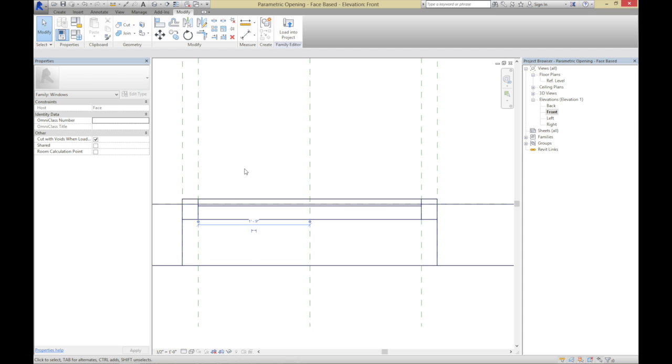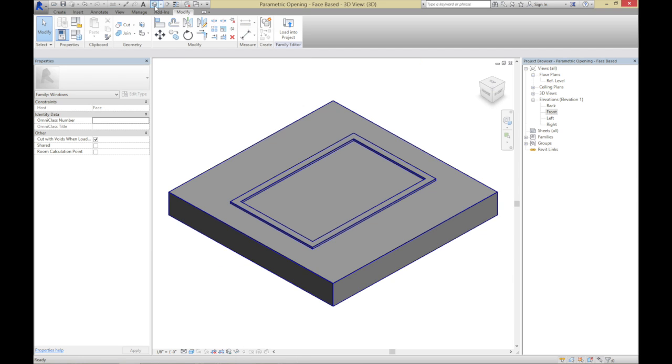And again, we can go through and choose exactly where these want to be relative to the architectural effect we're trying to achieve, whether you want something inset or give it parametric control, if you want to have the ability to change this more readily as opposed to defining it in the family. Come back over, it's looking pretty darn good, except for one important feature. You'll notice that it's all a bunch of this gray material, the default gray material, and we don't want that.